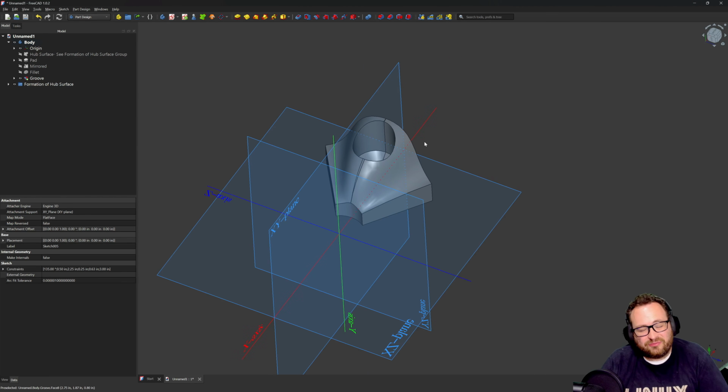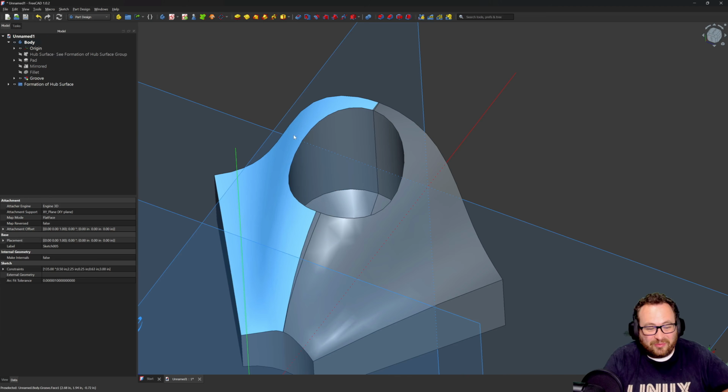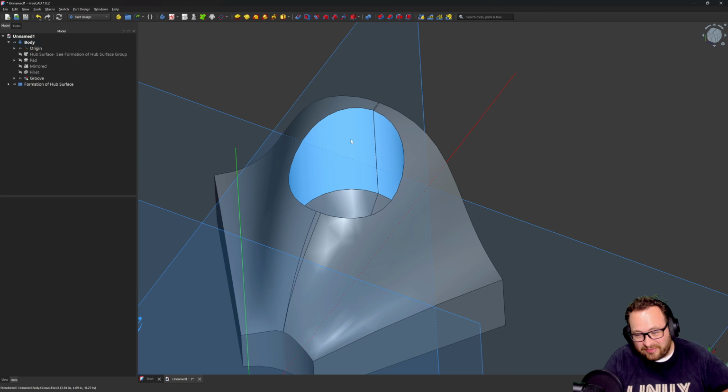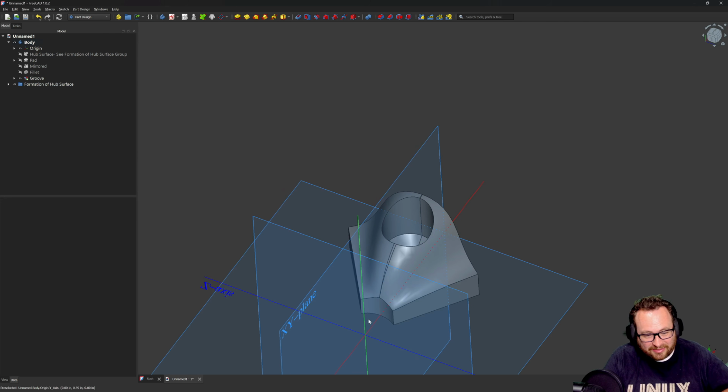Again, it is really hard to know when to fillet something and when not to. If in doubt, save your fillet till the very end. I'm going to break the rule a little bit and put some fillets on while I know that I have a pretty simple model and I can pattern these fillets, right? Because I'm going to pattern this hub. And perhaps patterned fillets are going to be great for consistency. So in other words, if I don't fillet right now, after patterning, I'm going to be putting 5 fillets down instead of just these 1. So that's a consideration, right? But it's also a great strategy to save all your fillets till the end. Again, it's up to you.